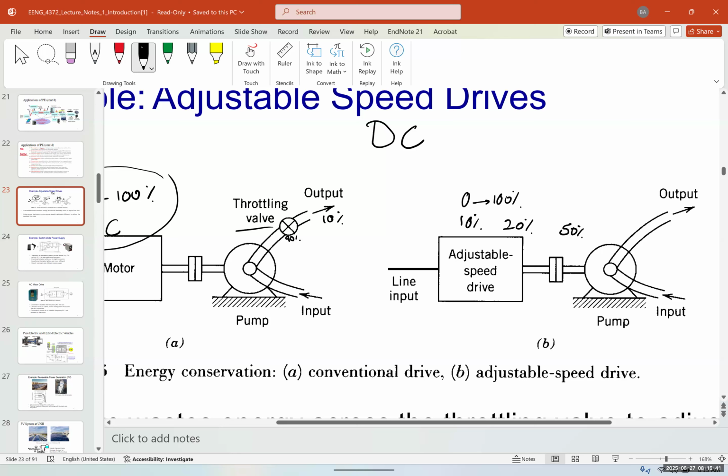So for a DC motor, if you want to control the revolutions per minute, you would control the input voltage, okay? So imagine you have a motor which is connected to a battery, and that itself creates a lot of problems, and I'll explain why. And this is an adjustable voltage supply, and you can move between, let's say, 0 and 12 volts.